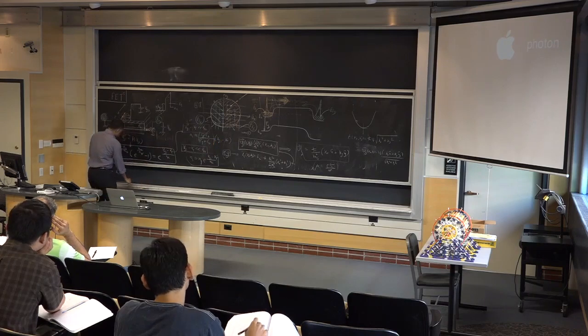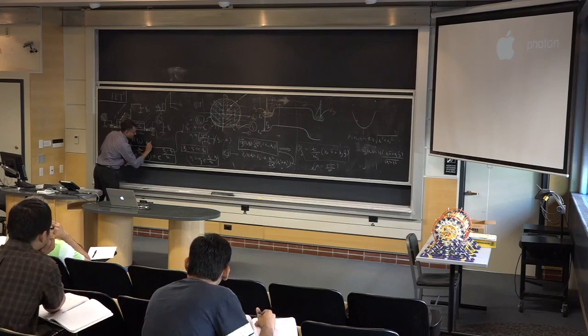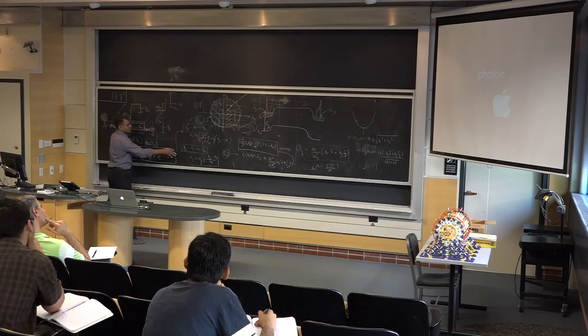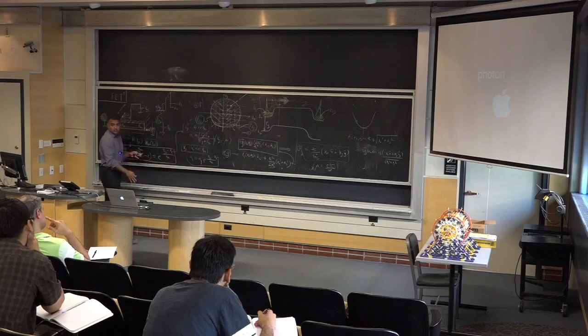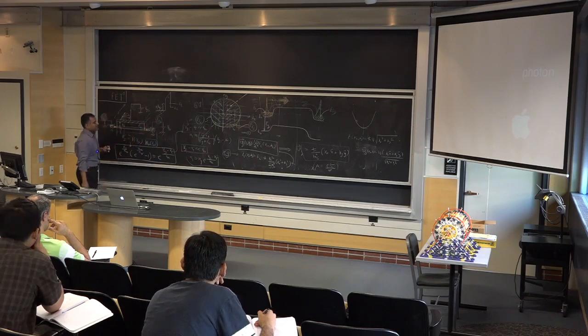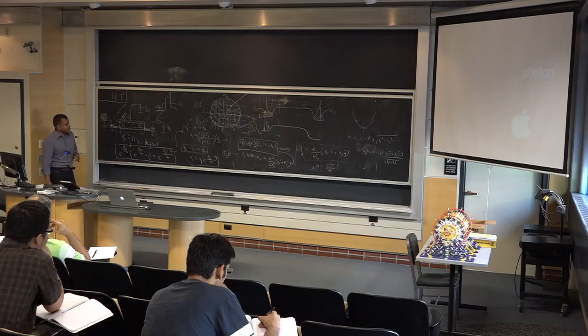And the solution to this equation, let me just label it as carrier density as a function of VGS. That's kind of the solution. That includes all situations, on state, off state, all that. This is a functional form. That's all I'm saying. Remember, log scale turn on, and then a polynomial saturation. So this is the carrier density as a function of gate voltage.